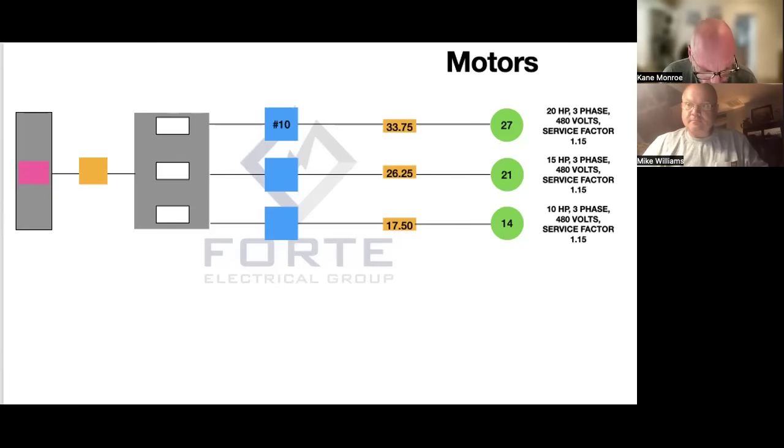What that's telling you is number 14 is only good for 15 amps, number 12 is only good for 20 amps, and number 10 is good for 30 amps. I'm paraphrasing the notes below. So 26.25 is above 20 amps, which tells you right away that number 12 won't work. You got to bump it up to number 10.